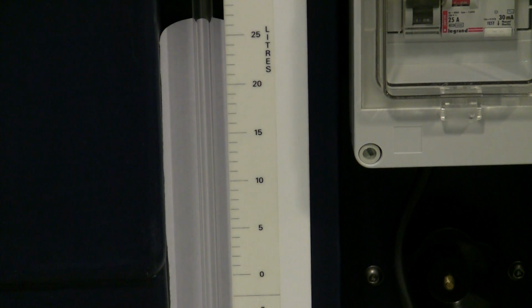Since the flow rate is lower here, it's going to take longer to accumulate, so you may want to use a reduced volume for calculating so it doesn't take so long. Note when it crosses 0 or some other point of reference. I need to reset. I'll be starting my measurements at 5.